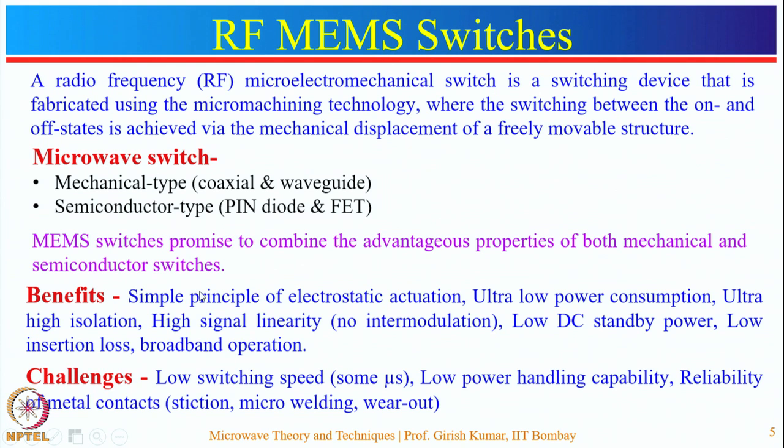The benefits of these switches are they are simple and they can operate in a simple way through electrostatic actuation. They provide the ultra low power consumption. The isolation is also very high in these switches. They provide high signal linearity and low DC standby power. The insertion loss is also less in these switches as compared to semiconductor type,